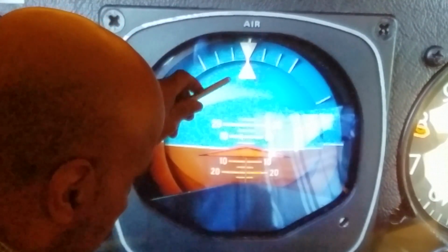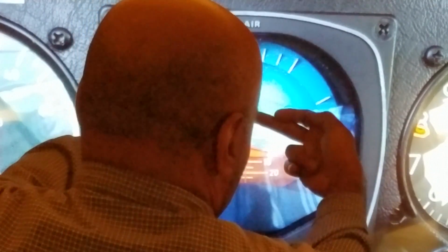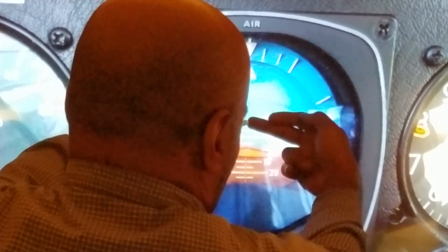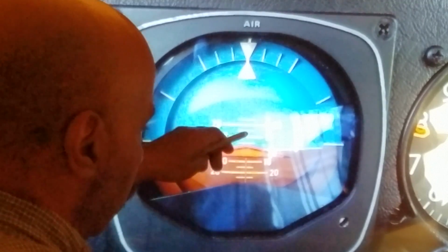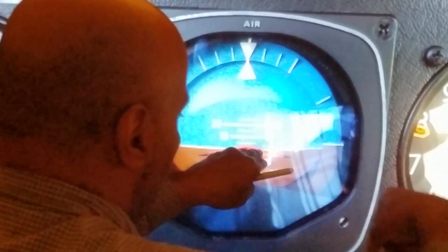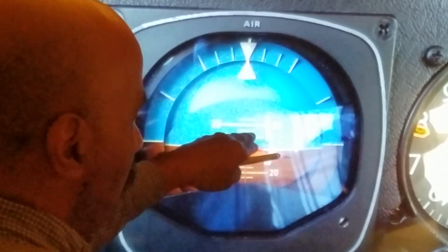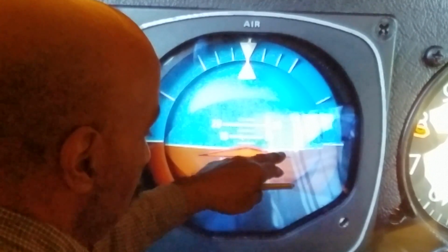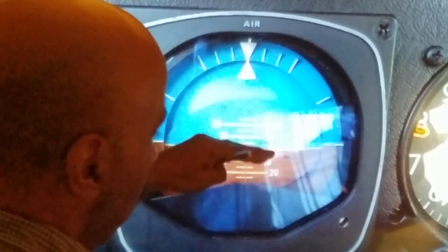The V bars would come down to a certain position on the gauge, and my hand is supposed to be indicating the V bars that came down. If he wanted to go to a higher altitude, the V bars would come down to a position above where he is level, and then the pilot would follow that command of those V bars and tuck this V into the V of those two bars and hold that.